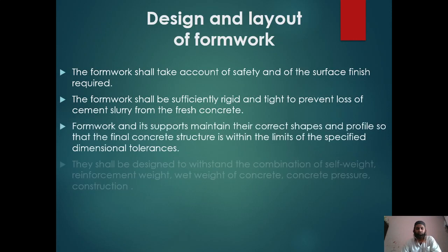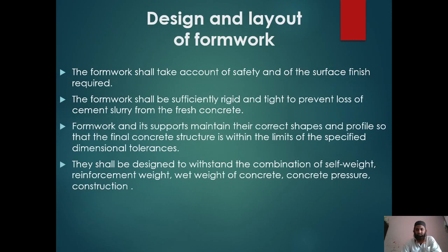Let us see design and layout of formwork. The formwork shall take account of safety and the surface finish required. The basic requirement is that safety is very much important. If we go for some old formwork which has been used for a long time, and it is not proper, and deflections take place with time in the formwork. You must have seen, if you go and see the formwork after removing it, after de-shuttering it, these formworks undergo deflection also. If they are not checked properly, and if we cast with the same type of formwork, then there are chances of unsafety and of not getting proper finish also.